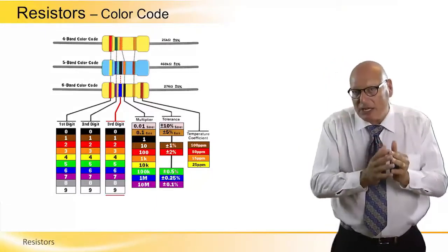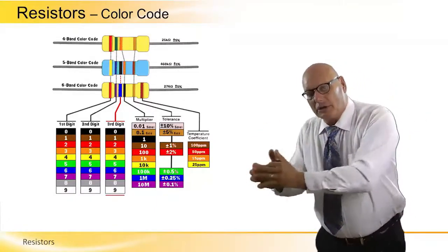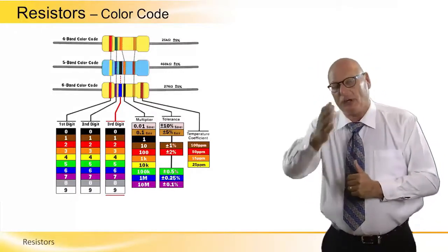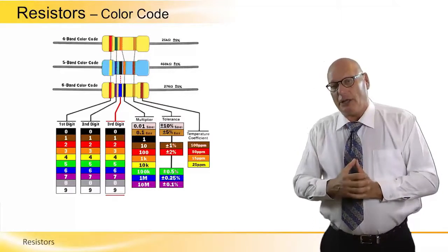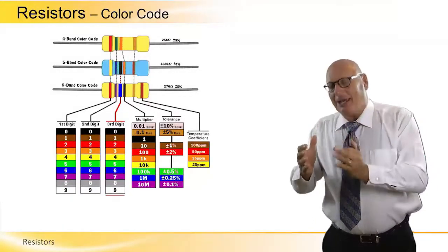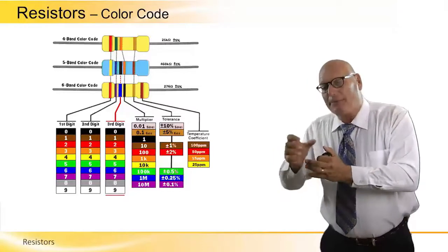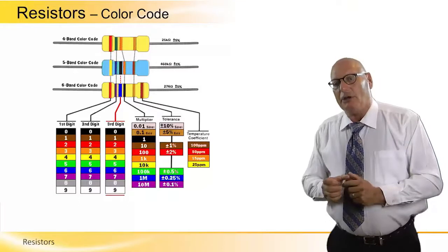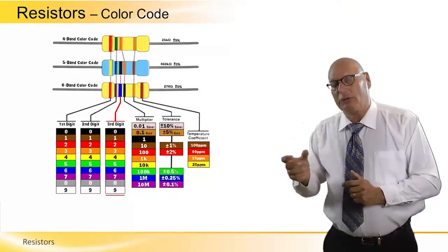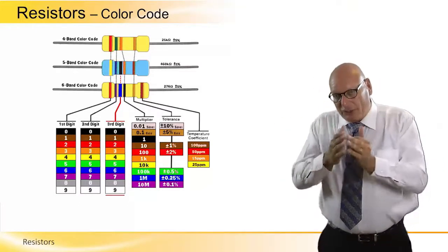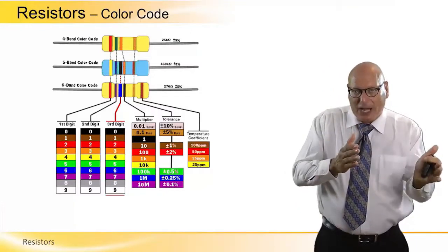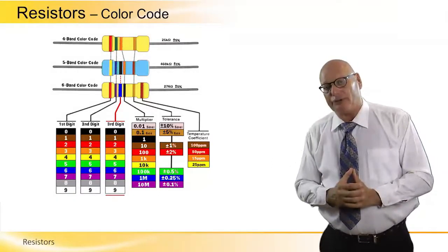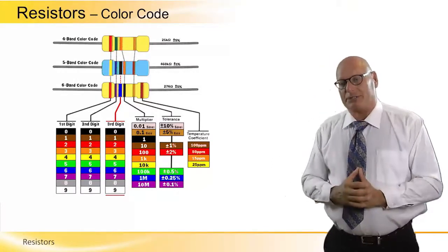So even if we say 25,000 ohms, 25 kilo ohms, because it's red, green, and orange, it actually says it's 25 kilo ohms plus minus, depending on the color of the tolerance. If it will be silver, it will be plus minus 10%. So the 25 can be anywhere between 22.5 to 27.5. The nominal value is 25. Now let's look at the tolerance.